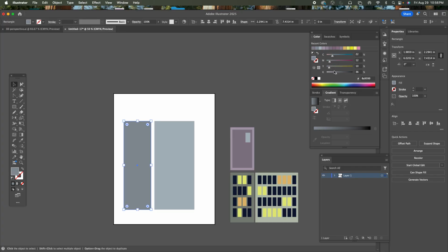The other thing, I don't know if I told you about this, but here's the deal. If you have color in something, and I'm just going to say that color is going to be that side, I'm going to use my eyedropper so it's equal. What I'm trying to tell you is this. If you hold down your Shift key when you are changing your color, like hold down your Shift key and click on one of these sliders for the color, it will slide down the color in proportion, okay, which is really cool.